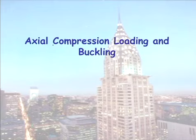Okay, moving on, because tension's the easy thing. It's compression. Because I brought my wonderful stick this time, what happens when I squash my stick? It buckles. We call that buckling. So members in tension, nice and easy, they yield. Members in compression, if they're long, they buckle. If they're short, so now I'm just grabbing over this length, they'll yield.